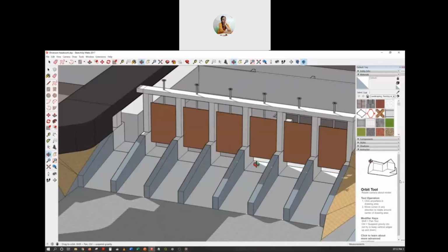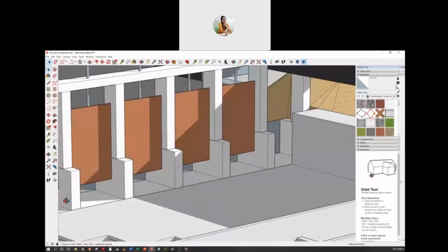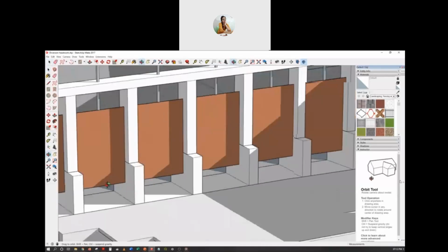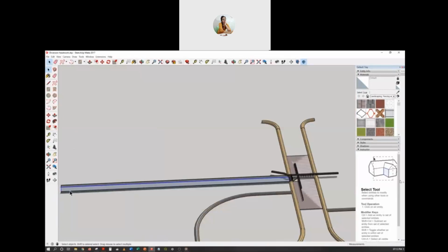Each of those gates is supposed to be opened by a different amount. Now, in this part, all the silt that is carried by the water will be stored and trapped, so that water entering through these openings will be relatively clear, and therefore in this canal we get cleaner water. So this canal will go a long way based on the command area.